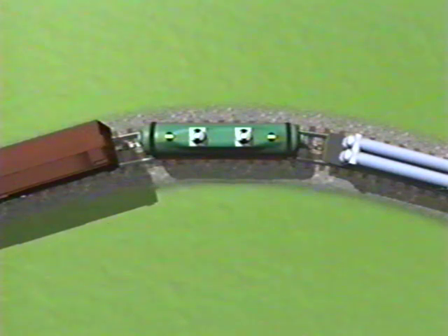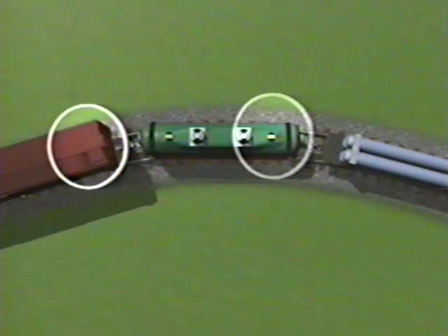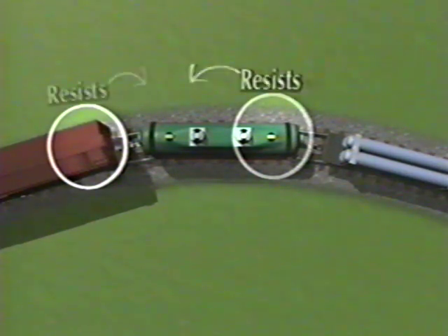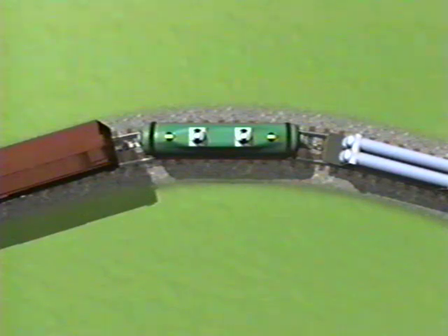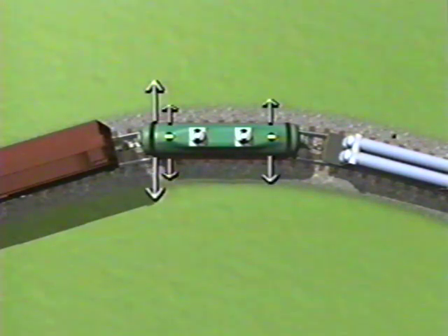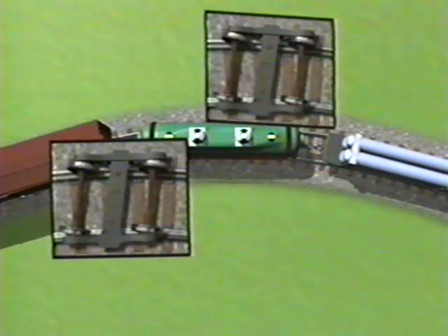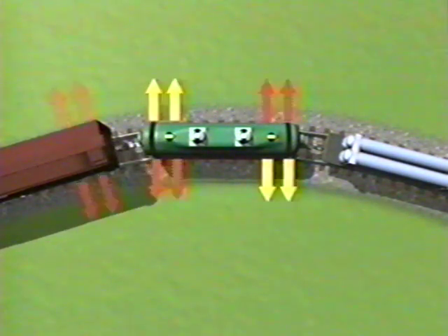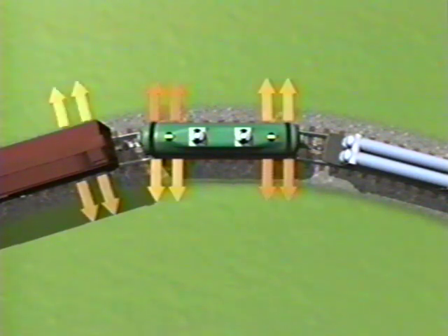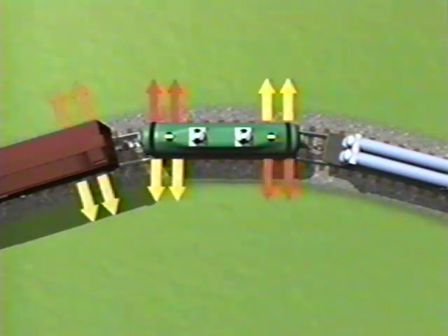Conventional cars, on the other hand, usually generate less gauge spreading force because a trailing truck that is steering properly will act to resist the rail rollover caused by a leading truck that is warped. For a conventional car that is curving properly, the lateral force pattern would look like this. However, if the trailing truck is warped or not steering properly on a conventional car, then it will act with the leading warped truck to produce high lateral forces that may potentially roll or spread the rail outward.